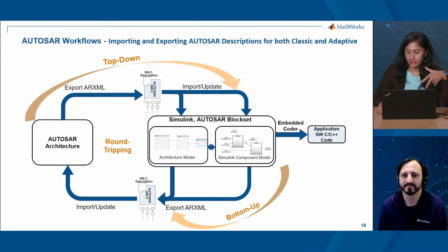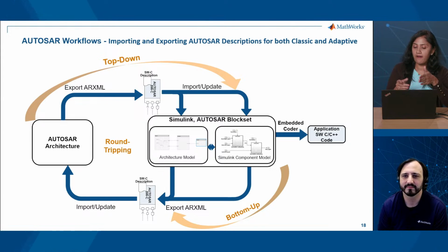When you import that into System Composer, it will create a skeleton of it, and it may not have a model created for it. You can create a model from an architecture. That model could be a Simulink model, and then add in your logic, internal behavior per se. Then it will be complete to generate code and AR XML.